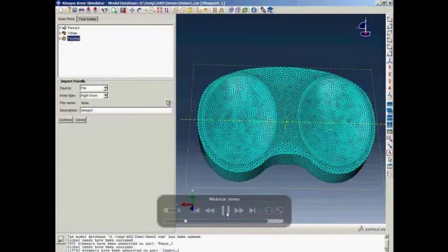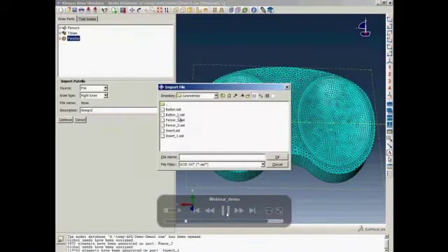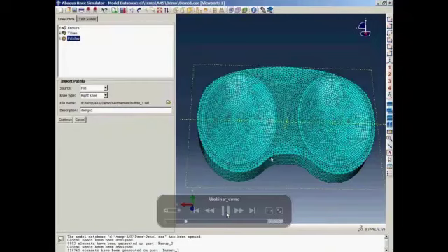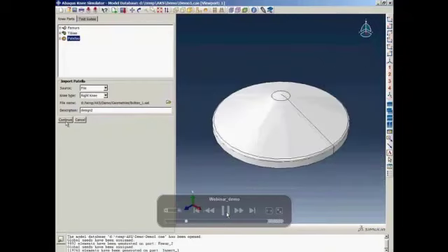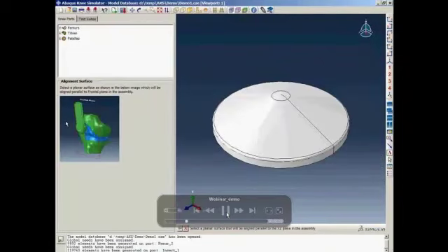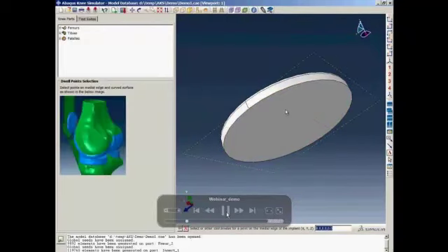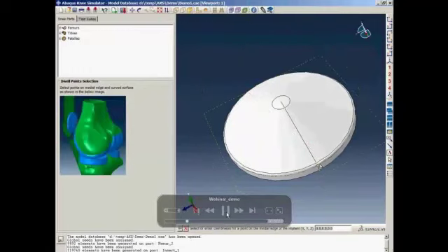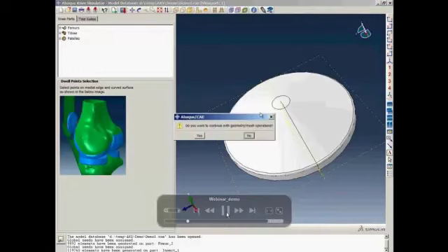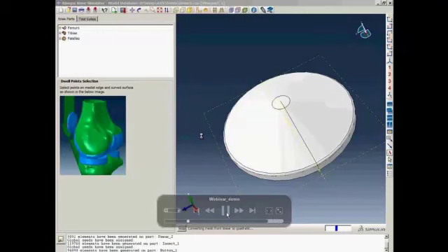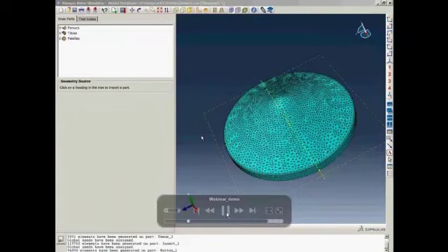Next, we import the patella button components. Again, one planar landmark is required, and 2 landmark points on the patella button, one on the medial edge and one on the curved surface. Again, the user can either mesh it in Abaqus Knee Simulator or just skip this for a part that has already been meshed.